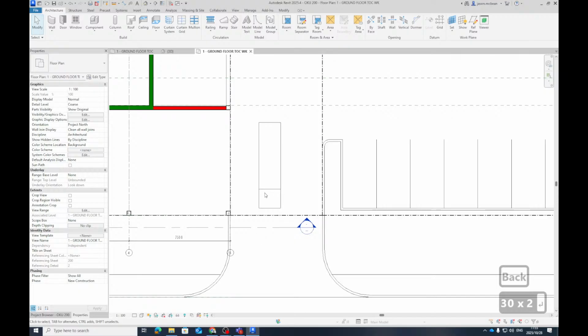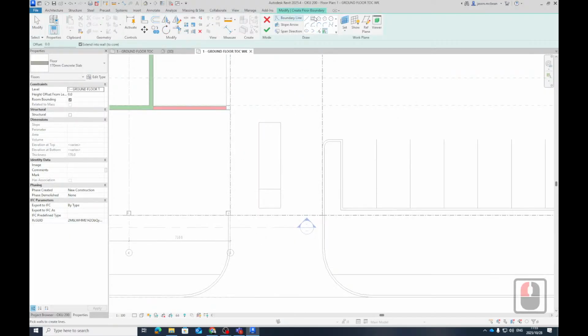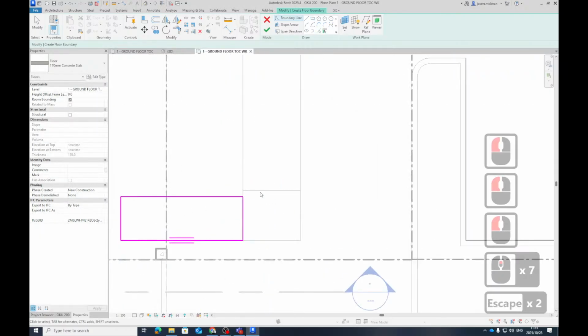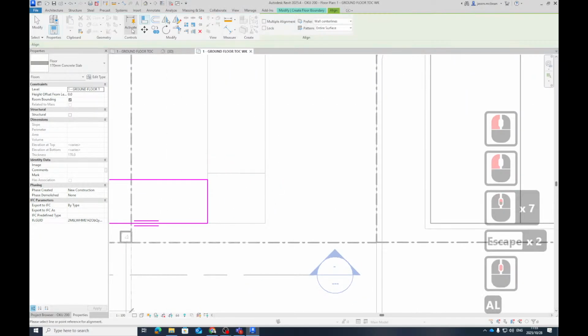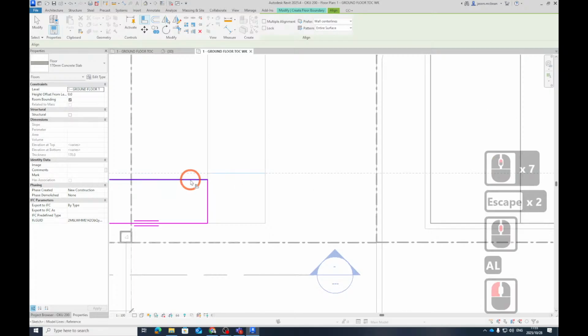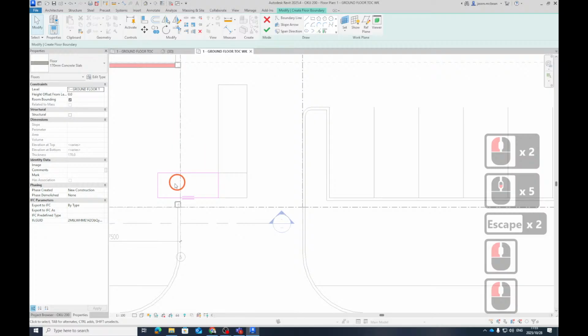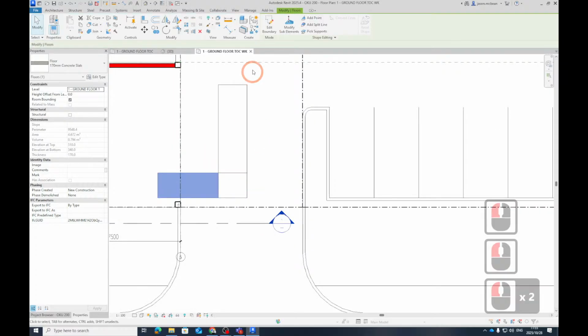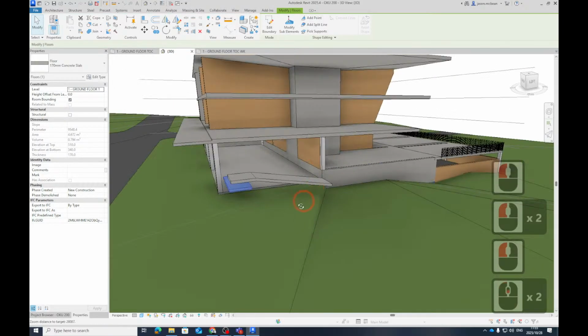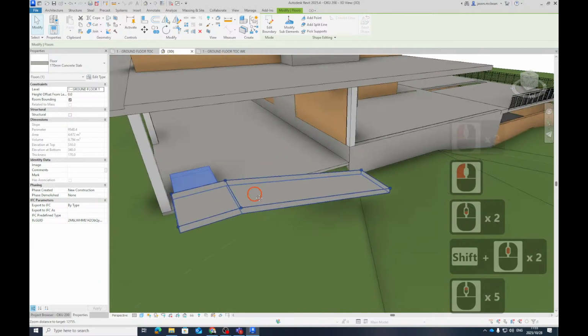higher, and you can make it look deeper as well. But I'm going to create another floor here. I'm going to make another floor that goes from there, and then go align commands, align. So you're actually using little floors, and they don't have to be thick. Pick a floor slab, or duplicate one that you don't have. What's neat now in 3D view, let's go back to 3D view. Watch what I can do. This is actually so quick.